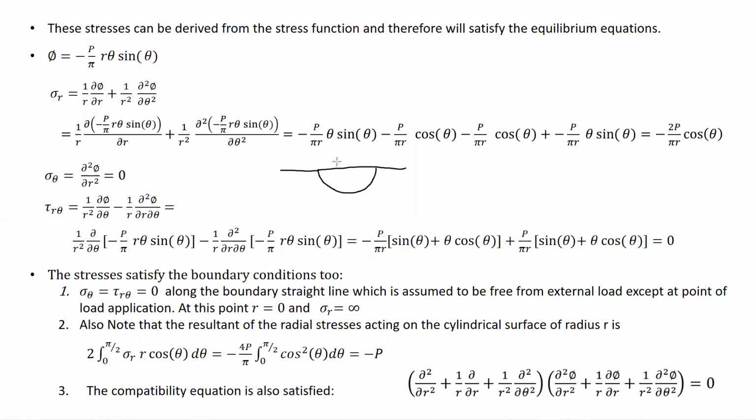So this is the load applied here, and this is my semi-infinite body. And I cut a circular thing here, and I study equilibrium of this semi-cylindrical body cut from the material with the external force. So this is the external force, and on the circumference of that circle, we have all the radial stresses applied.